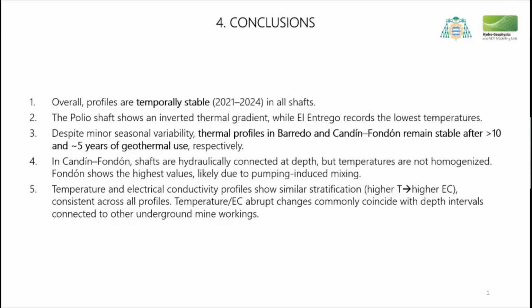In summary, thermal profiles are temporally stable, but spatially variable. This variability is mainly driven by pumping and hydraulic connections at depth. In interconnected systems, shafts may behave independently near the surface, but converge at deeper levels. And finally, temperature and electrical conductivity provide consistent information about mixing processes.